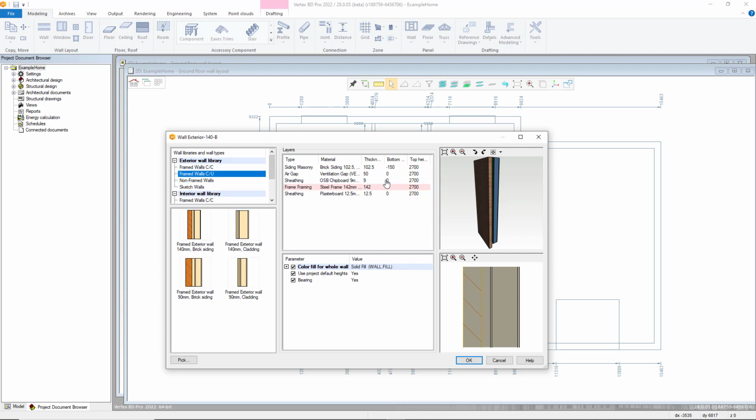This tutorial we will choose an exterior CTU framing wall. Within the layers column we can see the various materials and their respective thicknesses used within the wall structure. There is also the wall height per layer as defined per the Z levels shown here. Each layer has different options dependent on the layer type selected and alters the variables accordingly. These can be manually adjusted.